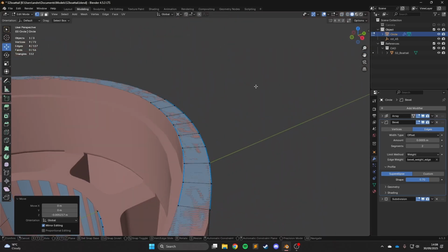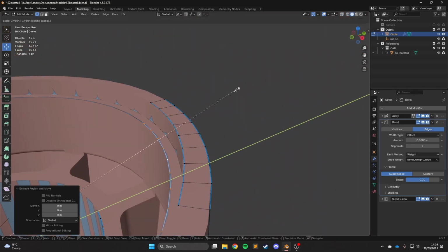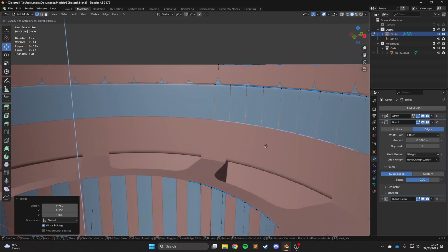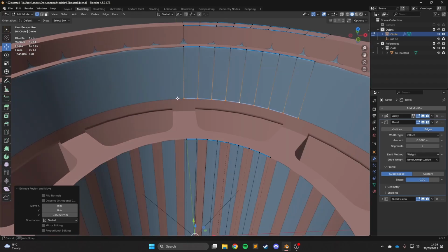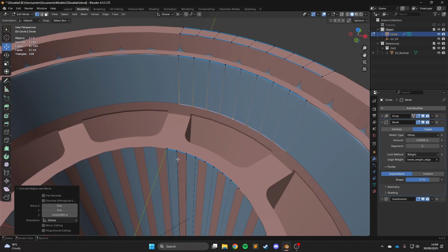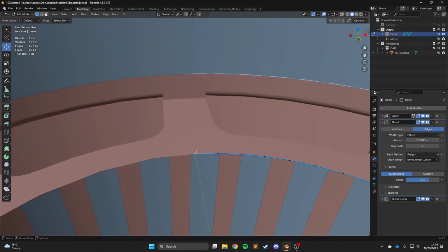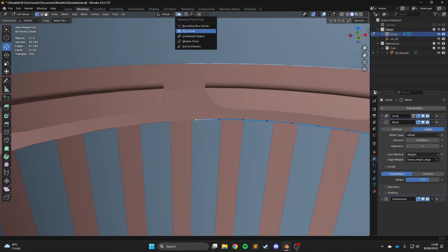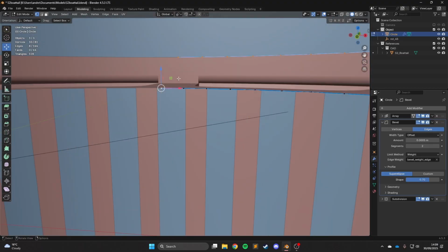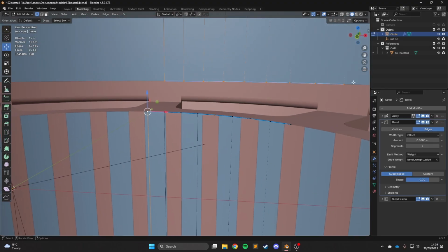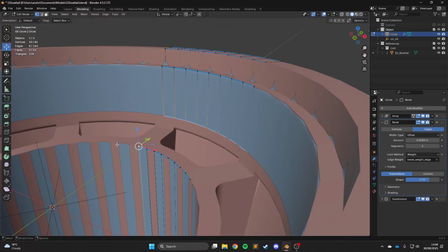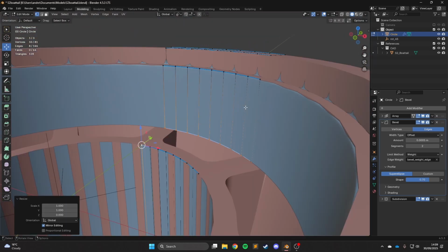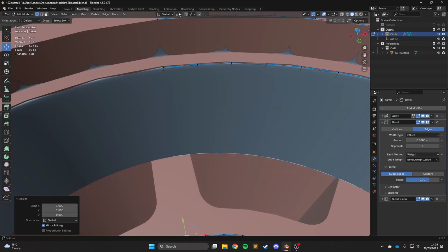GZ, bring that down there. GZ, bring that out. It's a bit there, and then what you can do, because these are on the same mesh now, once you've selected this, make sure you're in vertex select mode, shift select something that you want to bring it onto the same level as. Instead of the 3D cursor, you can set the pivot point to active element, so it'll be essentially the last thing selected. So you see how these are all orange and this one's white, and the lines are kind of lighter yellowy orange. That means that's the active element.